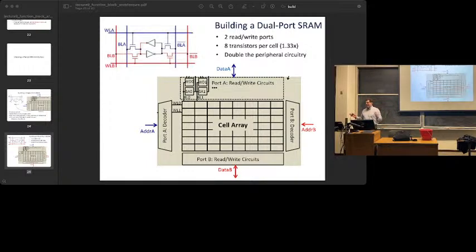What happens? You don't know, right? Nothing good, okay? Some unknown data will be written. The vendor data sheets basically say don't do this, because while the RAMs physically can do it, it doesn't make any logical sense. So in your design, you should make sure that never happens.